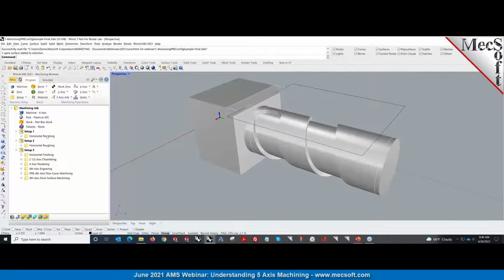One other note that I should make is about 5-axis. When we talk about 5-axis machining, you're always going to be using that in combination with 3-axis methods, because there's a lot of power in locking the tool axis and machining with the locked tool axis. And there's a lot of toolpath methods we have in 3-axis that you can leverage. So seldom will you machine everything using 5-axis. There's always a combination.